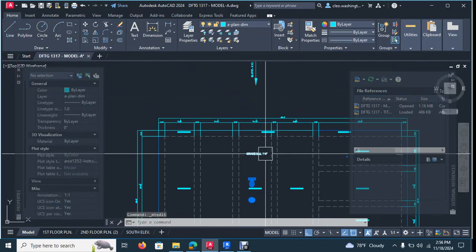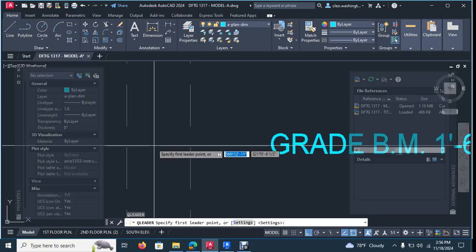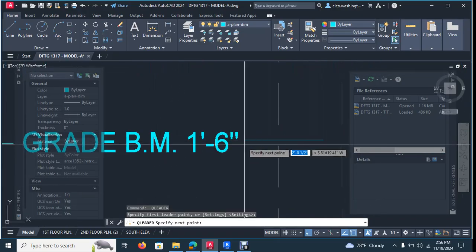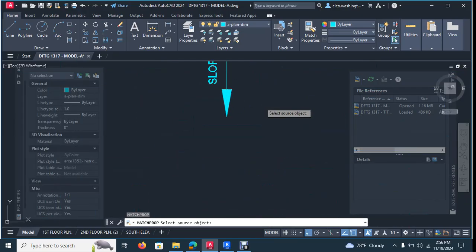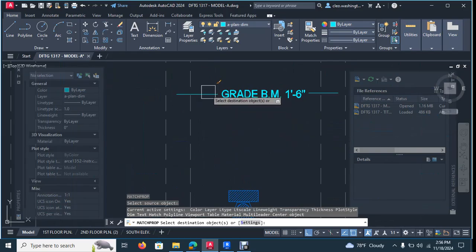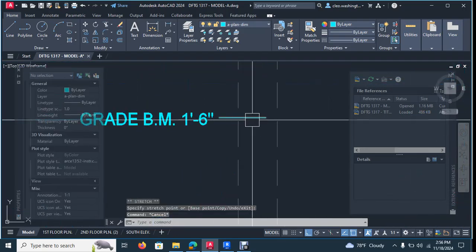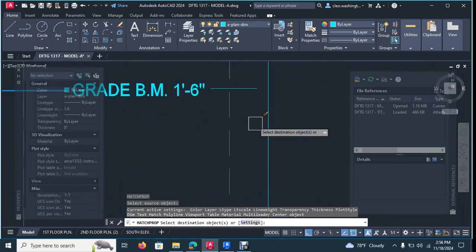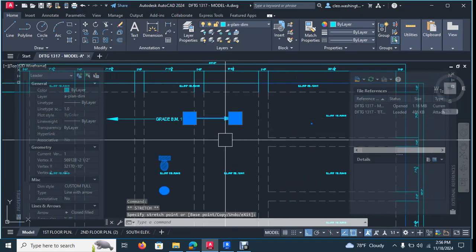Okay, and then you'll come here, you'll say draw LE, type in LE for a leader, draw a leader here, then you'll draw a leader here. And you want to match the leader that we just copied, right? But then we're going to change it because that leader head is just way too big. If you match a leader and the line is not long enough, it's not going to show. So what you got to do is take this line and drag it out some.